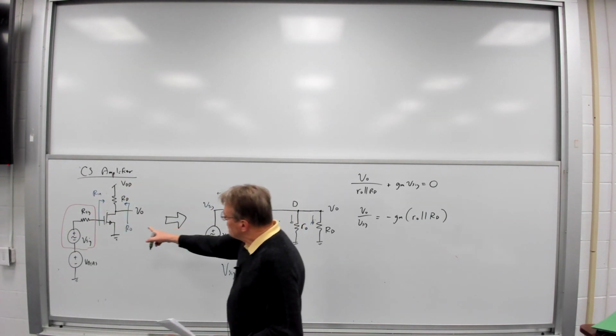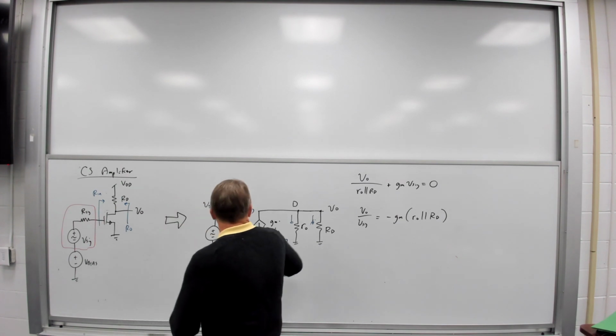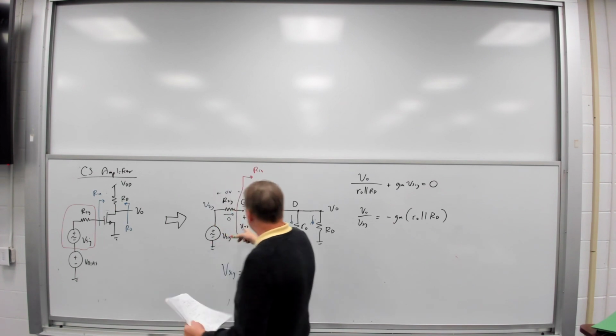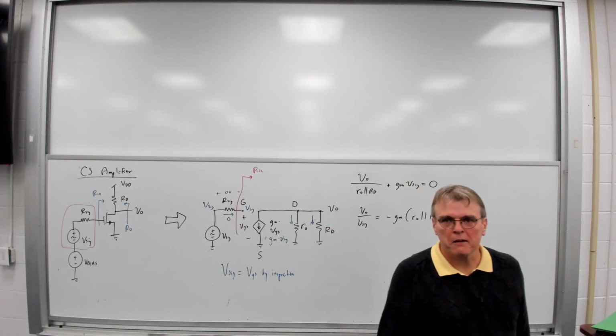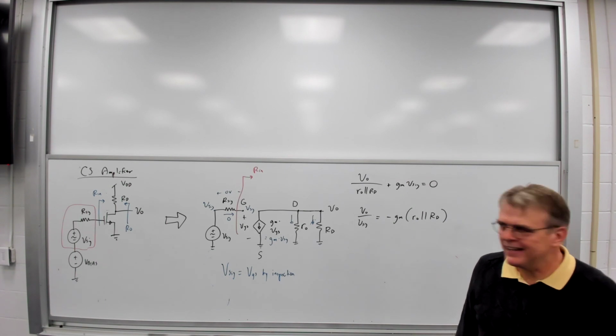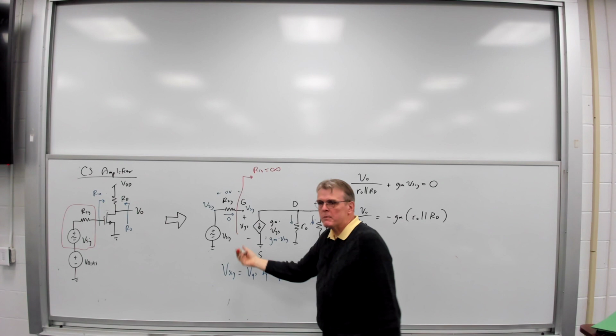What is the input resistance of this? Okay. What's R_in seen looking into there? What's that going to be? Infinity, yeah, right? It's an open circuit. So R_in is infinity for this particular topology.